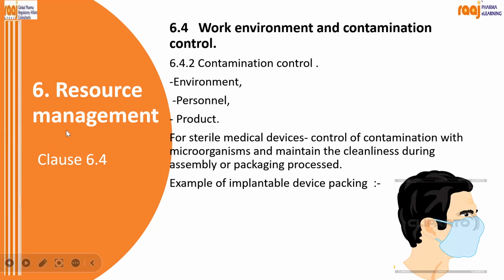Sometimes for sterile medical devices, you need control of contamination with microorganisms and maintenance of cleanliness during assembly or packaging process. For implantable device packing, you should maintain that cleanliness. In a sterile area, if any microorganism is there, it may be a problem. So you must have seen the clean room concept, right? ISO classification: ISO class 8, ISO class 7, ISO class 5, based on particles per cubic meter. As per medical device requirement, you have to maintain that cleanliness in the clean room.